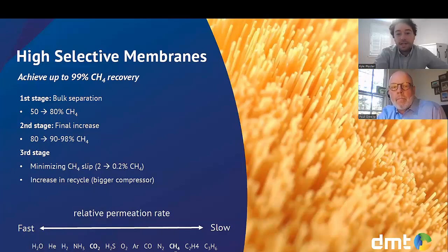So it's actually capturing more methane, and so we're not losing any revenue for these projects. Permeate is what goes through the membrane, and retentate is what the membrane retains. If you feed at maybe 200 psi, what pressure is the retentate at? The retentate retains the pressure pretty significantly. It would be a couple psi, maybe 10 psi less. Usually we like to say if it comes in at 200, to be safe, usually 180 psi coming out.